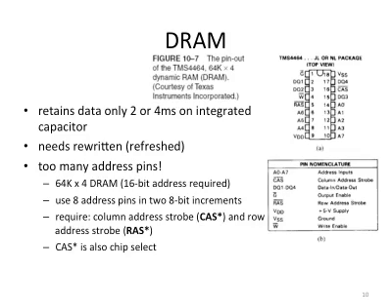It retains data only for 2 or 4 milliseconds on this capacitor. As a result, in order for DRAM to operate correctly for a long time, it needs to be rewritten, or so-called refreshing. So you need to periodically recharge the cell, the capacitor, to retain the content.